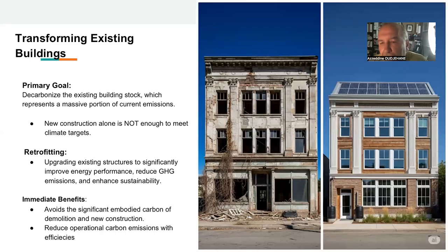Of course, when you're retrofitting, it's always going to depend on the state of the building you're retrofitting. And I used on purpose a building that's almost due for demolition. One thing that's not always highlighted is that by retrofitting an existing building, you're not demolishing, you're not creating more embodied carbon. You're using an existing building and enhancing it, because remember, the embodied carbon is locked in the existing infrastructure. So that's one thing to remember, retrofit versus demolition.